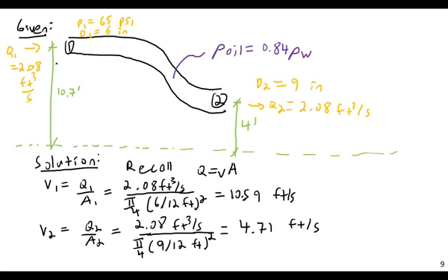I'm going to use the appropriate pressures here, in pounds per square inch. So just running through Bernoulli, I'll have 65 psi, pounds per square inch, times 144. Now here's the tricky part. Watch out for your conversions: inches squared per feet squared, or square foot.